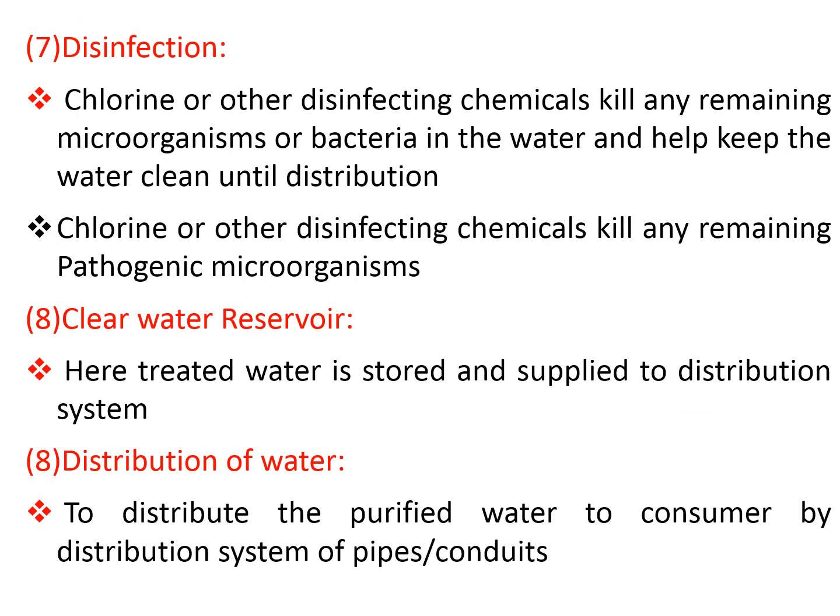After filtration, the most important treatment that comes up is called disinfection. Disinfection is the killing of microorganisms, and for that certain chemicals are to be added. The widely used chemical in India is chlorine, due to its good disinfecting power as well as its residual effect. Once treatment is given in the water treatment plant, the water has to be supplied to the distribution system.